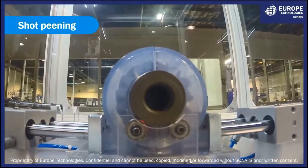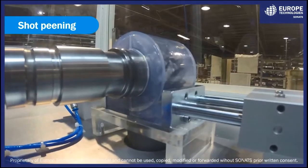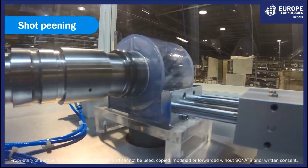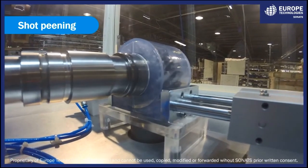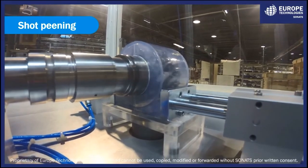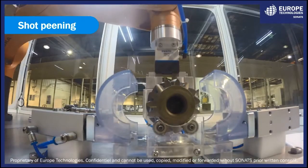So you see the motion of the media, ceramic media. There is no need for masking or unmasking operations to protect other areas from peening. Usually for industrial applications, the enclosure is made in hard steel, and the other components are made in plastic or 3D printing to avoid any scratches on the part.